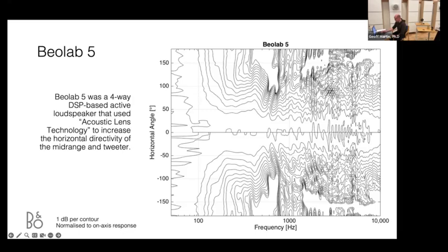And by the time we get up to something like 600-700 hertz here, we're about 14 dB down. So you can see that we really become narrower in that frequency range and then wider again. And what that means is that if you are 90 degrees off axis to the speaker, then you have a strange frequency response or magnitude response relative to the on-axis response of the system. So the more we can make these lines parallel, then the more the loudspeaker will sound like itself as you move off axis, and the more the reflection that's coming off the sidewall will have the same magnitude response as the on-axis.